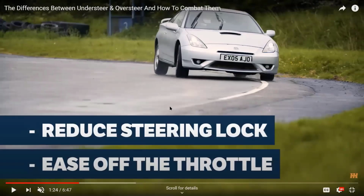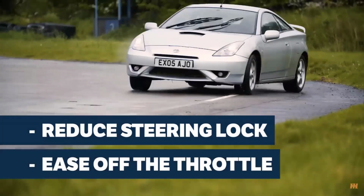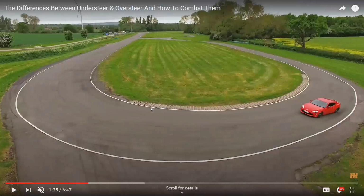Understeer can be recovered by, if we are making a 60-degree turn, if the steering input is 60 degrees, we need to reduce the steering input to 30 degrees or so. To make a small change in inertia, we should not give a large change in the steering. We need to apply the changes gradually. So we will be reducing the steering angle, and we need to remove the throttle up to a certain limit. We should not remove the overall throttle, because it will tend to cross over to oversteering. I will explain later. We just need to reduce the steering up to a certain limit, and reduce the throttle up to a certain limit.